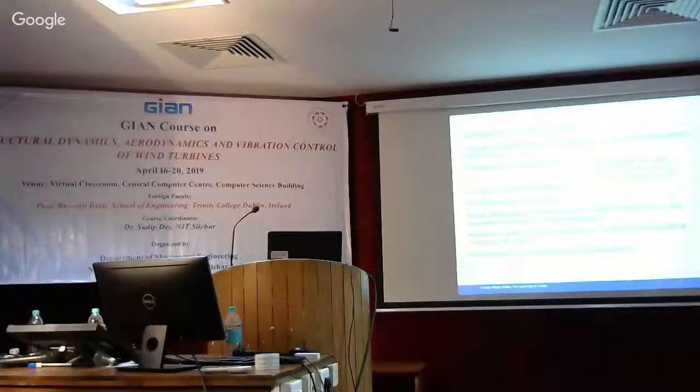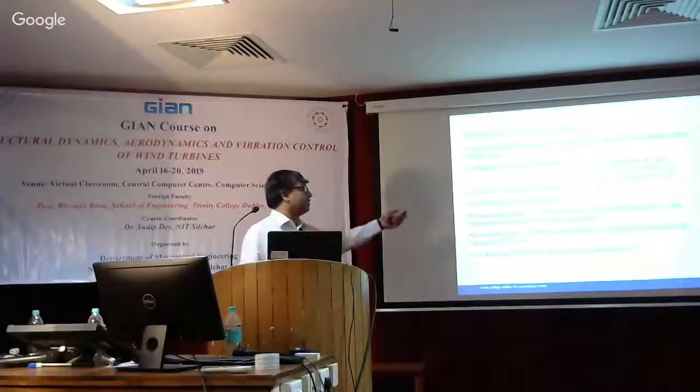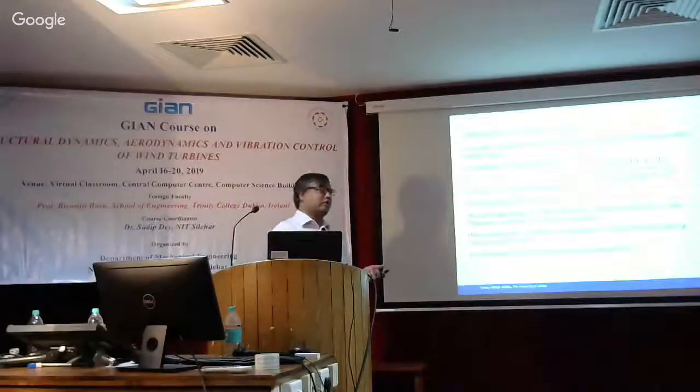You can do that by using a passive tuned mass damper, but you can also do it by using active controllers as well. So you can arbitrarily shape these shapes actually. And if you have a multi-degree of freedom system, your peaks look something like this. And then you can decide to choose filters, and you can shape this to say if you want to be like this, and then this goes like this, and you want flat, you can have some filters. Now, you can't do it arbitrarily, but obviously there's some rules you have to follow, and you can design some kind of filters to shape this. So this is really what we're doing in a more mathematical way, I would say. But again, to go through this, I mean, to go through a full course on control and design of filters and so on.